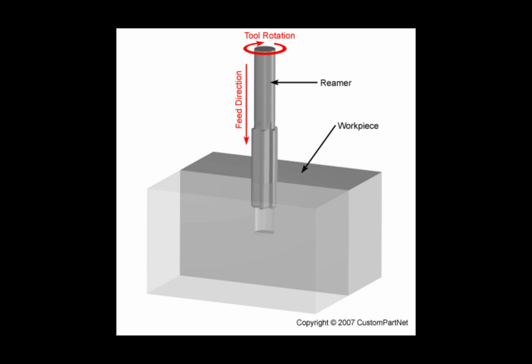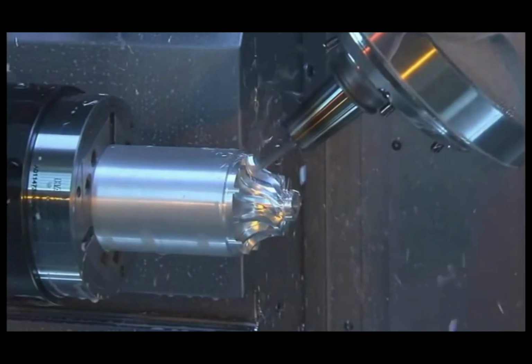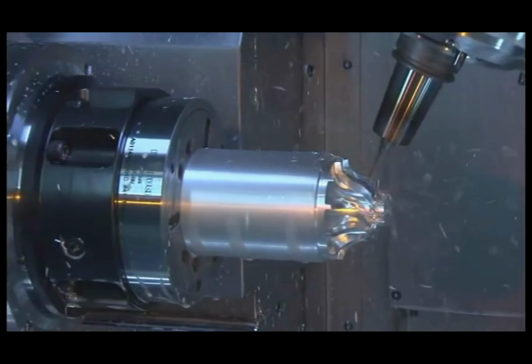Drilling, milling, and turning are all relatively inexpensive as long as the tolerances are not very precise. Reaming is re-drilling a hole to a slightly larger size for a precise fit and is more expensive. And operations like this one on a multi-axis machine are far more expensive than their three-axis counterparts.